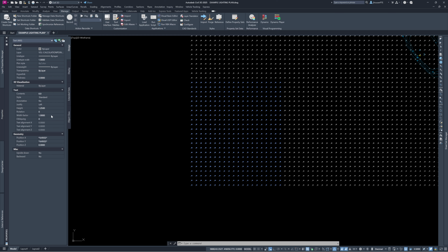A lot of times the text styles are not there because of the purging and such. So I would go into my Design Center and select proposed and visual style and then drag those into our CAD file. And now these are the contour labels for the foot candles. So I would select one of those, select similar. That gets them all. Then I can just go through and change my properties. So those I usually make white, and that would be a proposed.